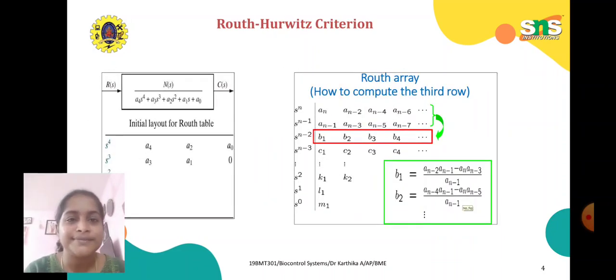See here, your input is R(s) and output is C(s). Here the transfer function is N(s) over a4 s^4 + a3 s^3 + a2 s^2 + a1 s + a0. Here the initial layout for the Routh table is rows s^4, s^3, s^2, s^1 with entries a4, a2, a0, then a3, a1, 0.